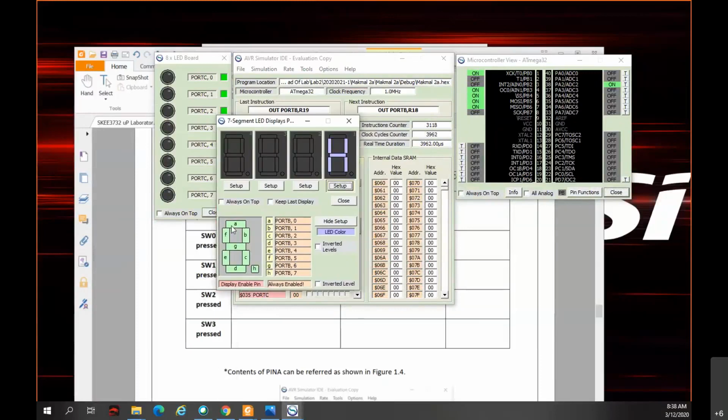Because our 7 segment display has 8 LEDs. If you look, A is your least significant bit, while H is your most significant bit. So make sure that A is connected to PB0, while H is connected to PB7. Then make sure that you use the common cathode. Why? If you use the inverted level, for example...